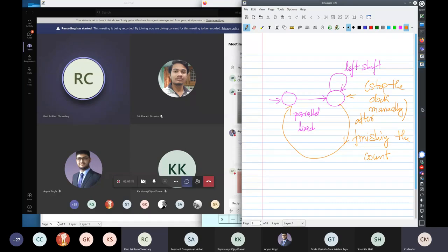Sir, there is also a problem in designing this state machine, because the flip-flops also have to get some initial value, right? Not from the combinatorial cloud. They have to be initialized first of all. You just check, because if you look at the design after the clocking is done, your inputs will override.